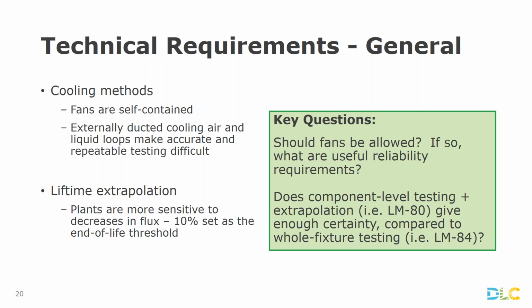And so for DLC Premium, general illumination side, we require certain characteristics of the drivers, that there needs to be a temperature measurement test on the driver, and then there needs to be documentation from the driver manufacturer showing that the driver, when operated at or below that temperature that's tested, will have a certain lifetime. So that combined with the chip level reliability or LED device level reliability statistics like TM21 gives a higher level of confidence in the product's overall life cycle.